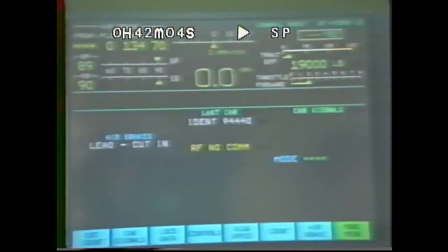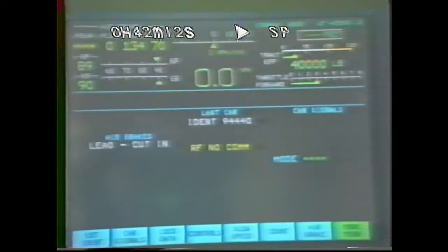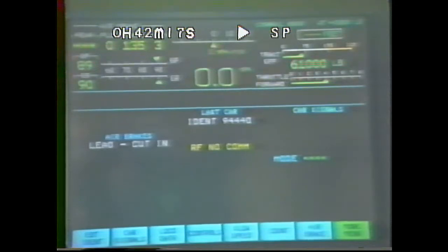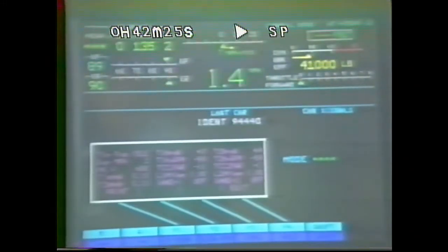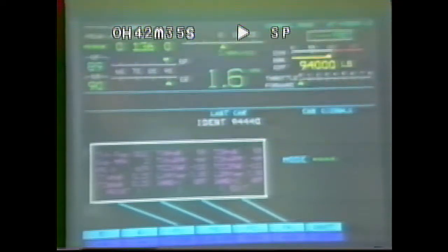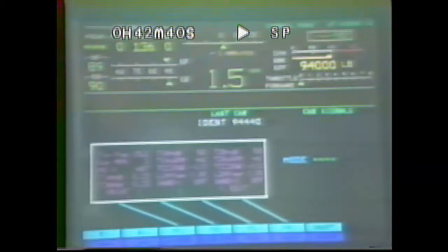You must keep the slow loading characteristics in mind when starting a train on an uphill grade. Make sure you've advanced the throttle high enough to prevent the train from rolling back before you release the brakes. You may even need to use a notch or two more than you normally would with DC locomotives in this situation. Because if the train begins to roll backward and gets up to 1.5 miles per hour or higher in the wrong direction, you'll lose the load and the locomotive's computer will command full dynamic brake until the train stops. Then you'll have to start all over again using a higher throttle setting.